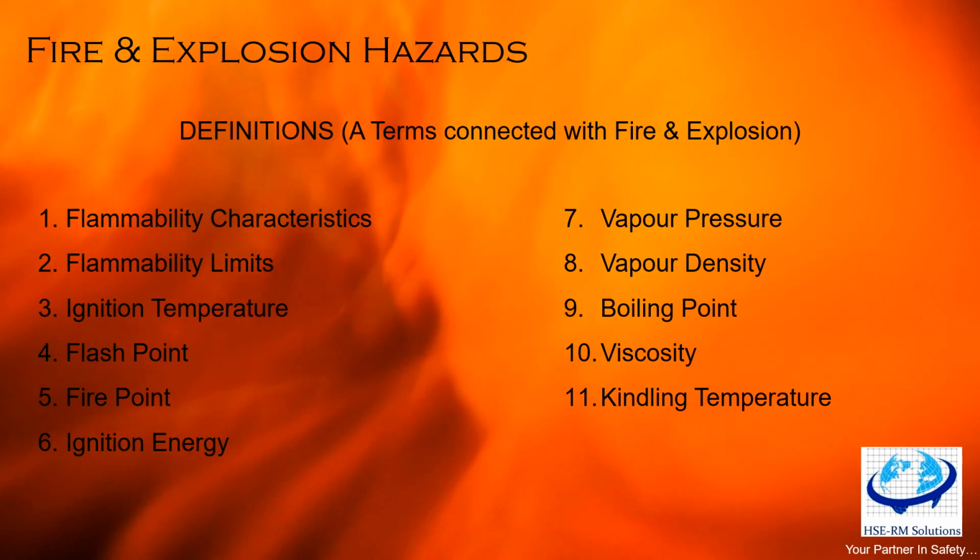So this is the basics of fire, wherein you need to understand the ignition temperature and flash points. Flash point means instantaneous higher flashes, immediate burns. Now coming to the next part, and that is fire point. The fire point of a flammable liquid is the lowest temperature at which the liquid, when placed in an open container, will give off significant vapor to continue to burn once ignited. The fire point is usually a few degrees above the open cup flash point.